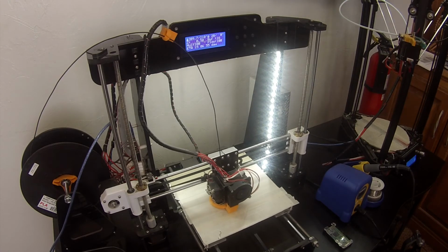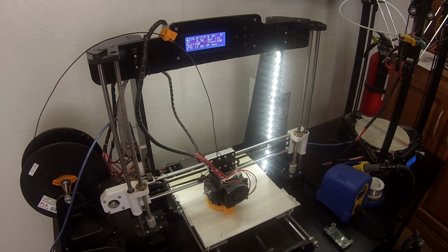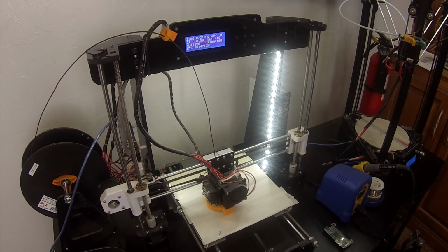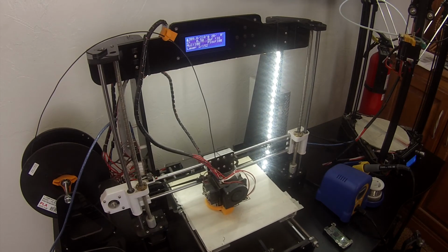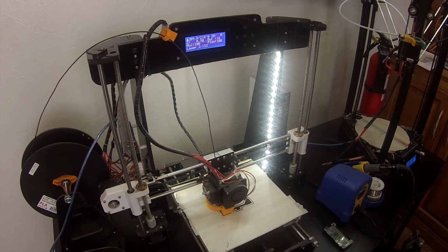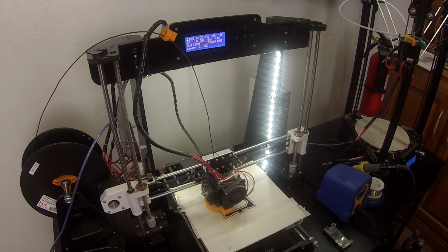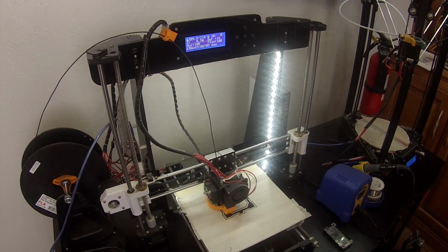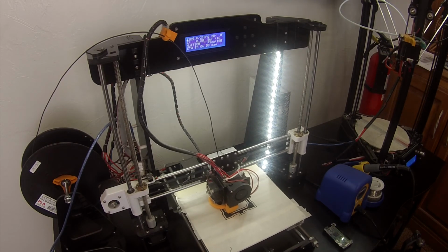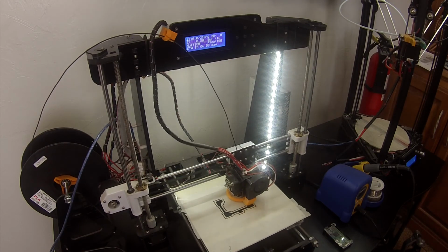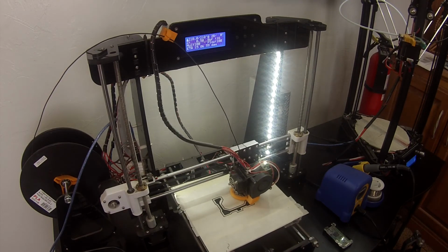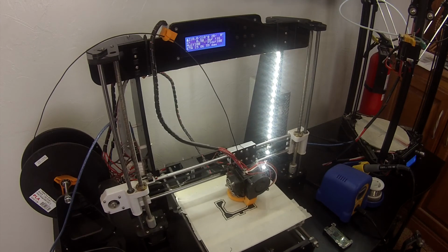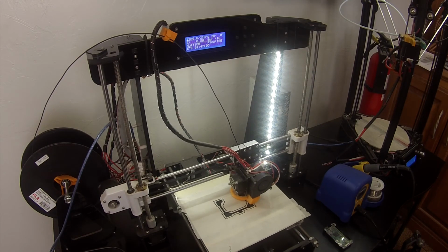There's also been some fires started by quality control issues with these boards. They're mass produced at very low cost. So observing these printers while in action, at least being in the same room so you could stop a small fire or unplug something if an electrical fire started is ideal. If the printers are in a non-flammable enclosure, then it becomes more acceptable to be distant from them. So that way, even if the printer does catch fire, it's prevented from spreading to the building surrounding you. That would make it more acceptable for standalone print use.